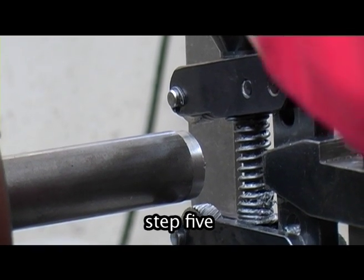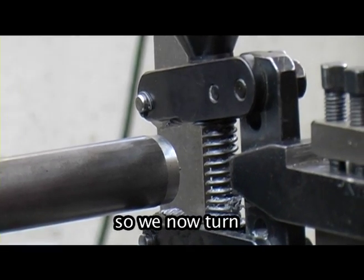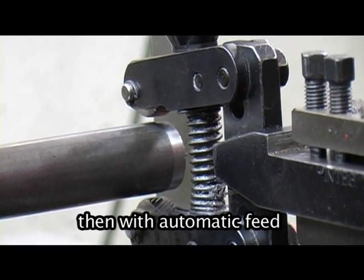Step 5, we're now ready to actually put the knurl on, so we now turn the adjusting screw of the knurling tool just 1/4 of a turn, and then with automatic feed cut the knurl.